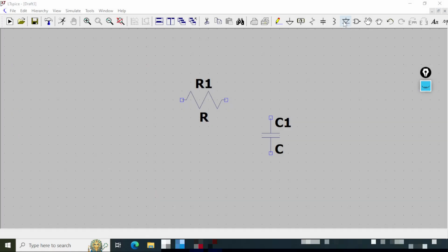Now I will draw one particular inductor and you can see it is in the vertical direction. I want to make it horizontal, and from the keyboard I hit Ctrl and then R. It has moved, right? But I think the arrangement is not suitable. So I'll rotate it once more and once more. Now this orientation looks fine for me. So I'll place it here with the left click, and with the right click, I'll make this vanish because I do not want any more inductor.